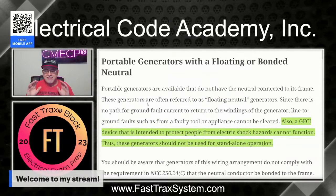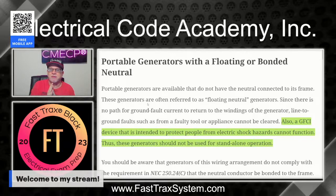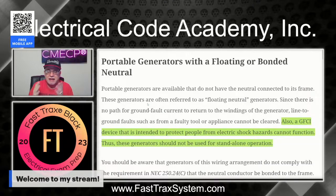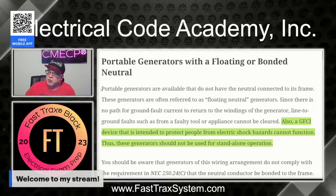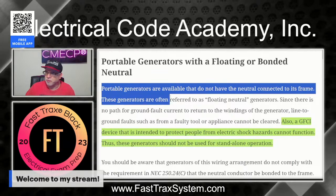That doesn't mean that it's not going to work and you're not going to plug an extension cord into it and get power. Obviously, you are. But when you need those devices to function safely and clear a fault, that's when the problem occurs. You might say to yourself, well, I've never tripped a breaker on my floating neutral generator. There's probably a reason why that hasn't happened. Portable generators are available that do not have the neutral connected to the frame.